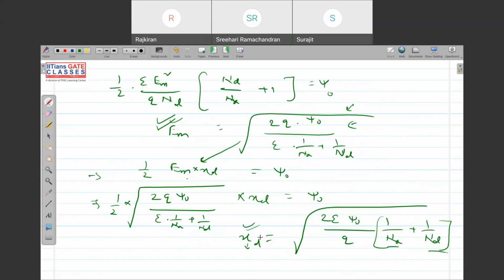Okay. So in that case, sir, what thing will make the constant? Means, will Vbi remain the same, or will the peak remain? Vbi also depends upon Na and Nd. Why will Vbi remain the same? If you increase doping, everything will change. Vbi will change, the electric field will change. Nobody is forcing me to make anything constant, right?